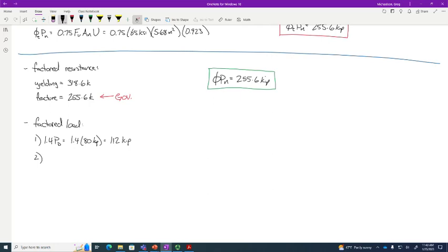What about our second? 1.2 times the dead plus 1.6 times the live. Those of you that have had concrete design, this should be pretty familiar, right? You've done these before, I know you have. 1.2 times 80 kips plus 1.6 times 9. And what do we get for this?